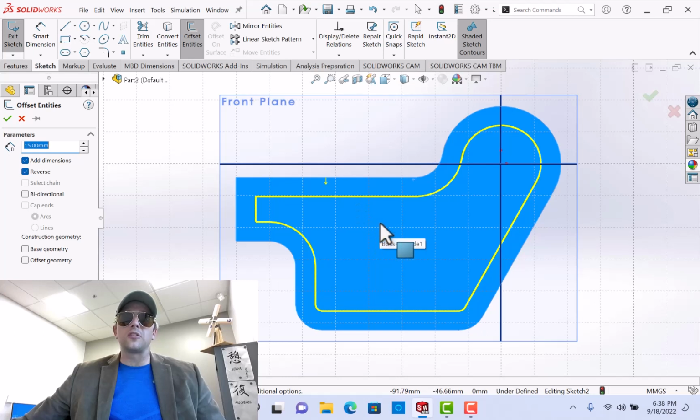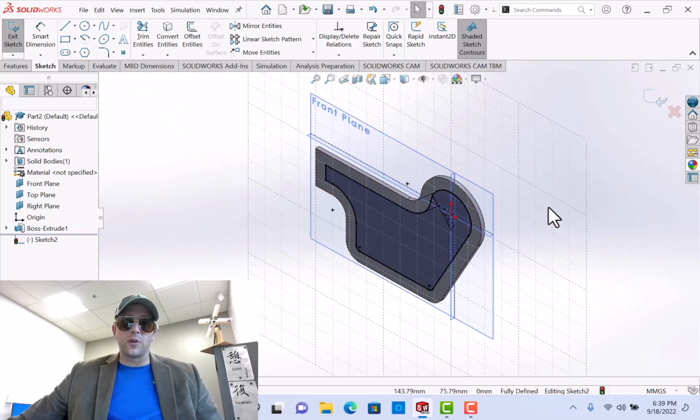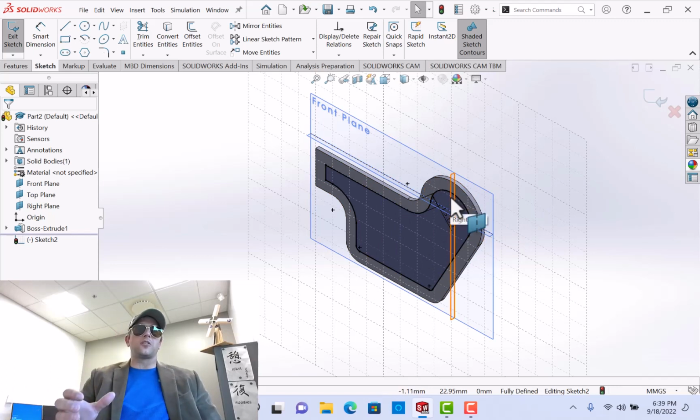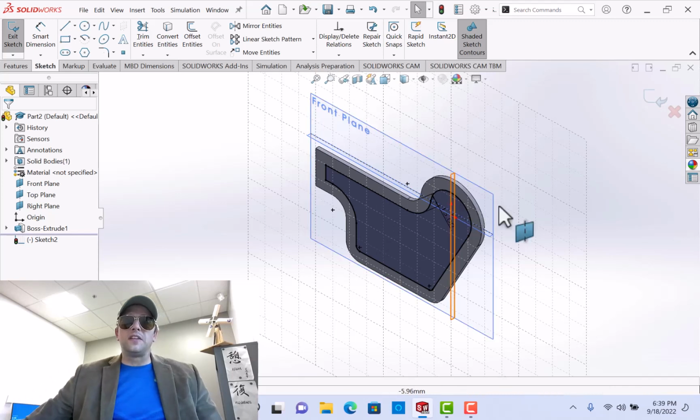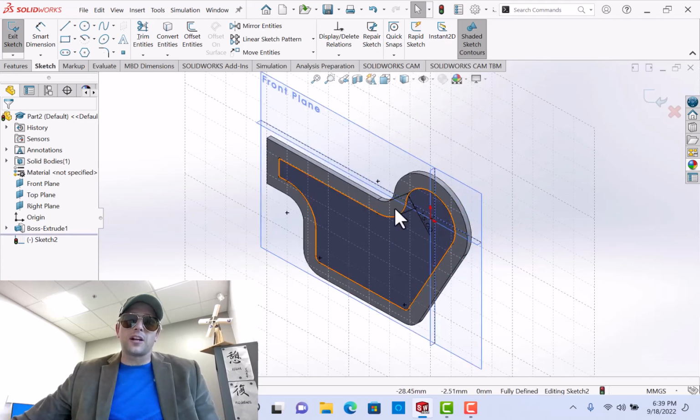So this way we have drawn a solid surface first, and now we're drawing onto that solid surface. We're drawing onto the SolidWorks part, and now we're putting a reverse direction of our offset as 15. We hit OK. Guess what we have now? What we have is something that's drawn onto the surface versus something that's the featured part, and when it's extruded, it only extrudes a thin surface. So that's the difference between the two things that we just did. It's subtle, but it actually is a big difference in how SolidWorks approaches it.